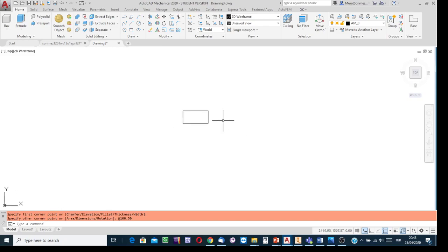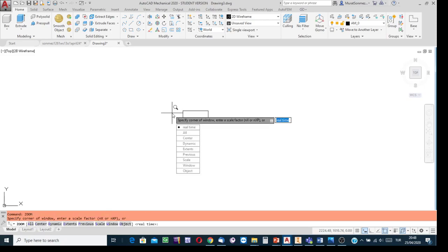Or, to be able to see the sketch in almost the size of the display, you can write this command, zoom, okay, press enter, and then click the down direction key, and from the list, you see whenever there is a little arrow within the first compartment, this means you can find some options.